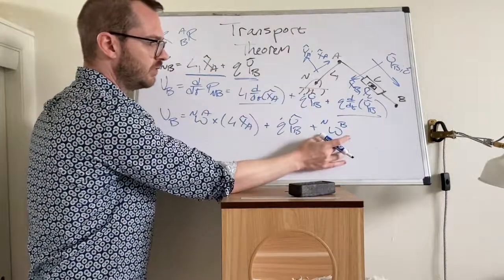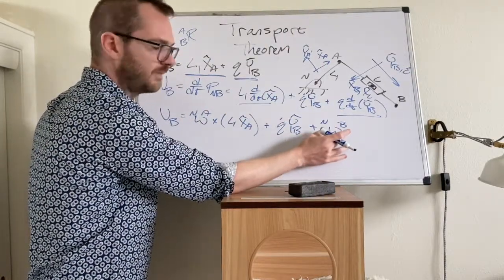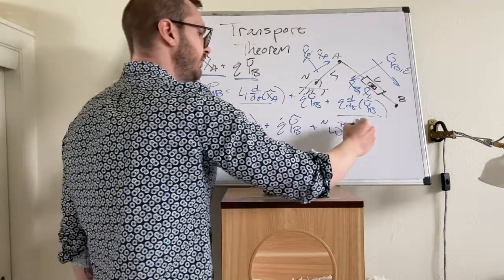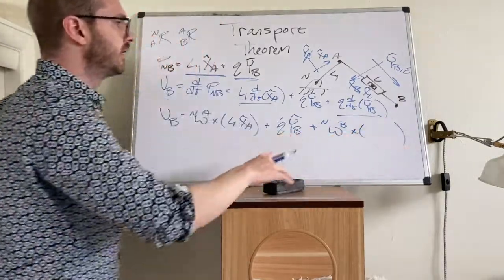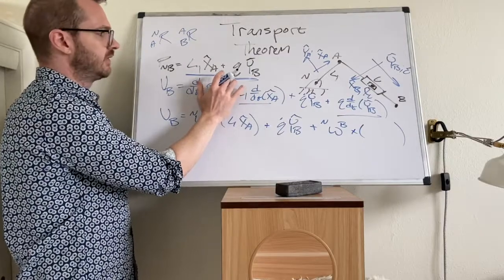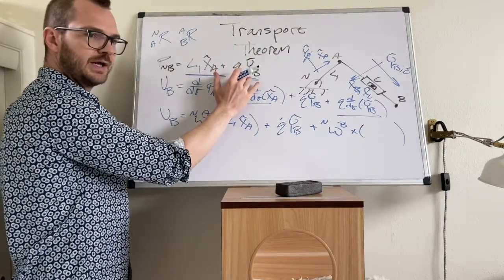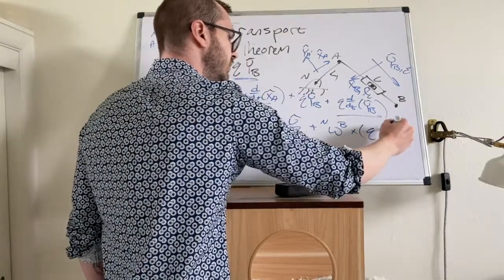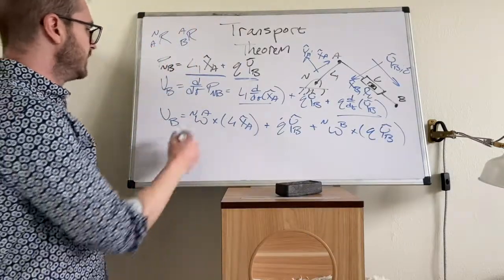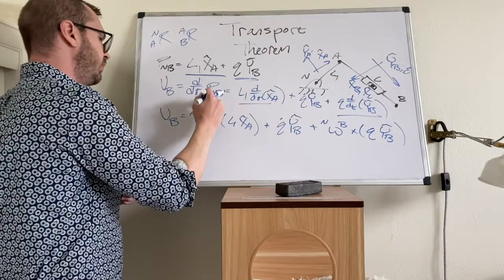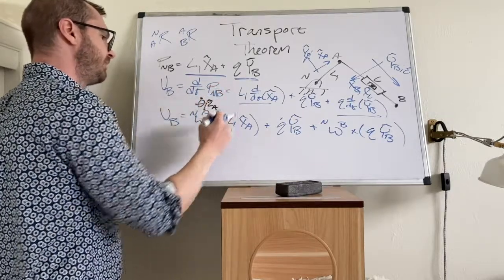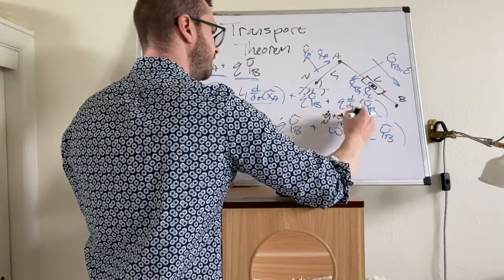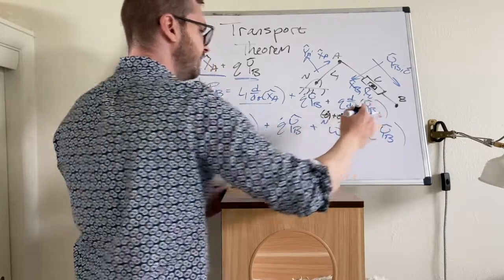We defined this one using relative angles. It doesn't affect this. It is still the total angular velocity of that frame. So omega into B, cross. Now, what do we bring down? We bring down this position vector, and it's a little different this time because we're defining it in the YB. That's okay. We bring this down, and now it's cross Q YB. Okay. What were these things? This was theta 1 dot ZA. This one now is theta 1 dot plus theta 2 dot ZB.